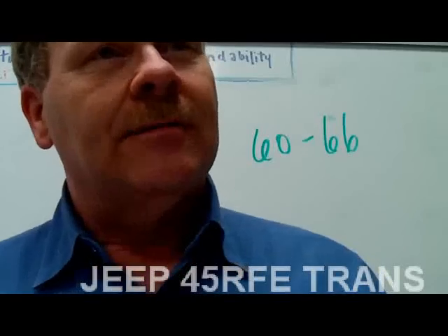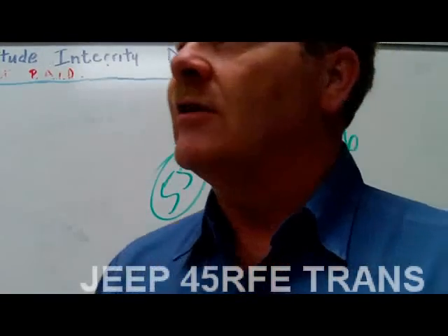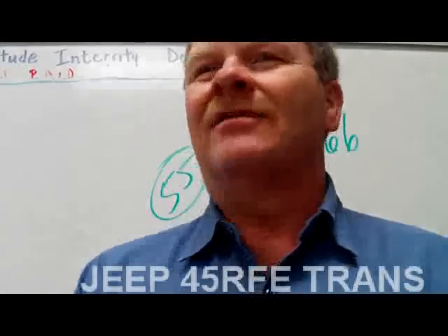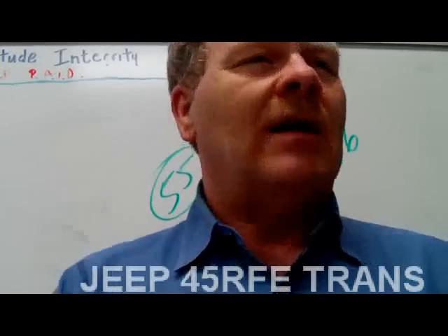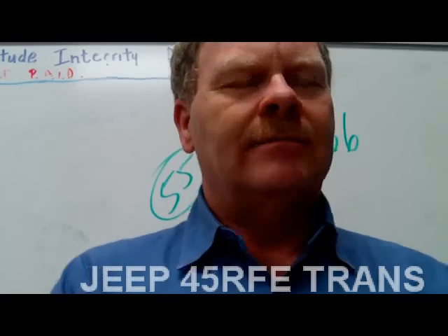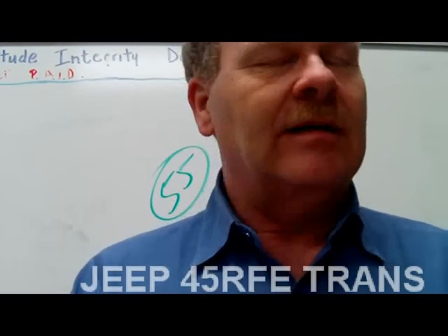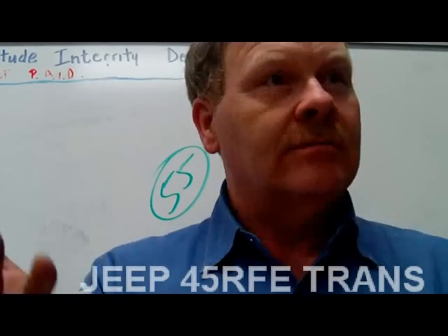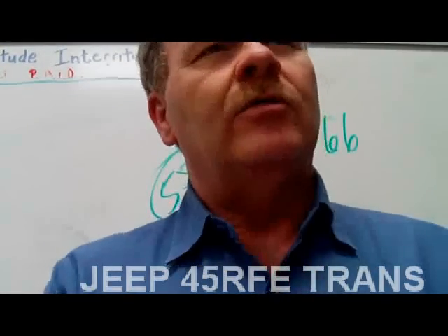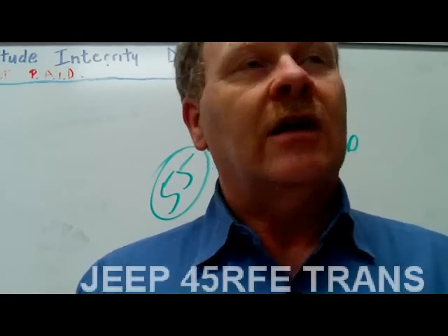I did a fluid change because the properties of transmission fluid change when it's been hot, and it gums everything up. Change the fluid, put a modulator valve on it, which is the vacuum operated deal that goes on there. It helps you hold your gears whenever you're at heavy throttle, low vacuum, high engine load, holds the gears longer. We put a new modulator valve on there because that one had a little oil. So we put the transmission cooler on, took care of the problem.